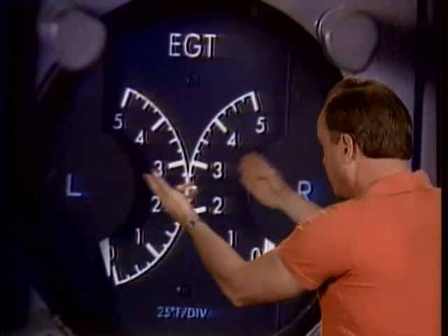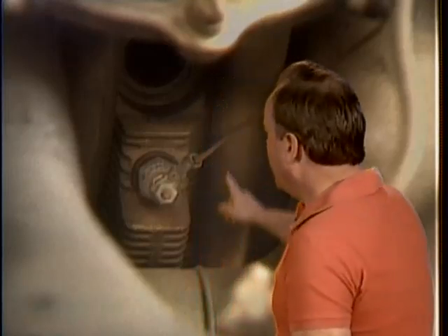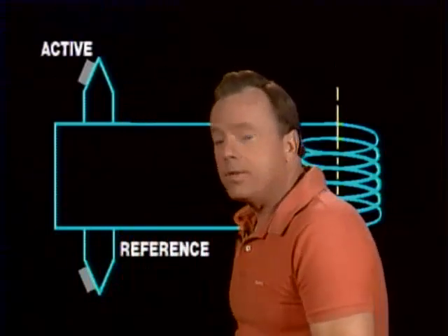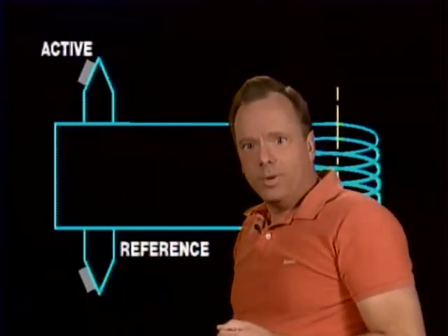So here's a case where you have exhaust gas temperature. You would have two galvanometers right there. All right, the indication of temperature in a thermocouple type cylinder head temperature indicator is produced by current then, generated by the temperature difference between dissimilar hot and cold junctions. And here's a case where you have the hot junction sensing the temperature there in a cylinder head temperature indicator. So they're going to say, okay, what determines the voltage output and therefore the current of a thermocouple type system? And it's determined by the temperature difference between the two ends of the thermocouple. You guys have got this nailed.